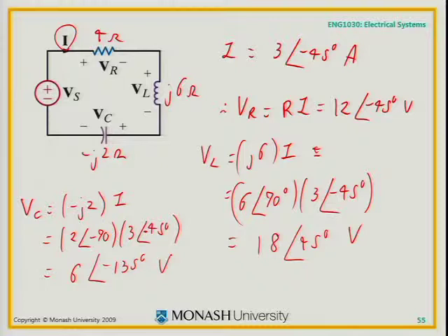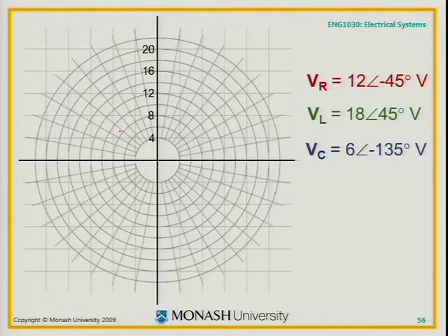I know the amplitude and the phase, and the rest is cos omega t plus the phase. Now this phasor diagram business just says, let's suppose, what should I know about VR plus VL plus VC? What should VR plus VL plus VC be equal to? Vs. Kirchhoff's voltage law around that loop. So let's suppose I wanted to show that. You might get a diagram like this, which is handy for angles and things. So there's VR.